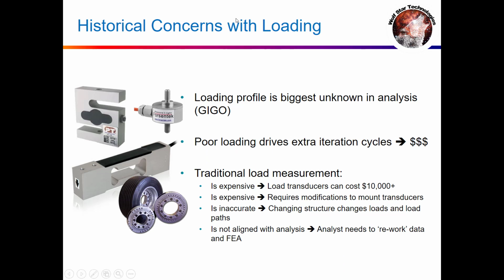So a little bit about historical concerns with loading. Any analysis you do, you've got great CAD geometry, you've got great meshing tools, you've got great material models, you've got great solvers, and the biggest unknown in the whole process is when you go to take your FEA model and submit it for a solve, it's basically a guess on your part oftentimes. So if you're guessing at the load cases, you're basically guessing at the solutions.